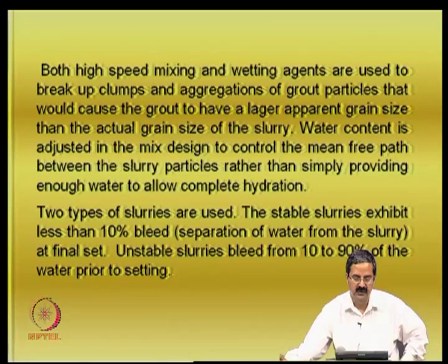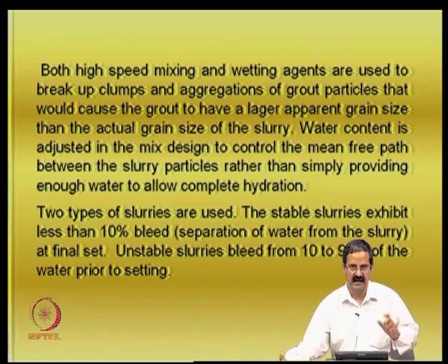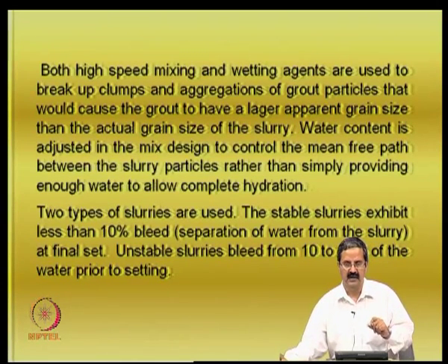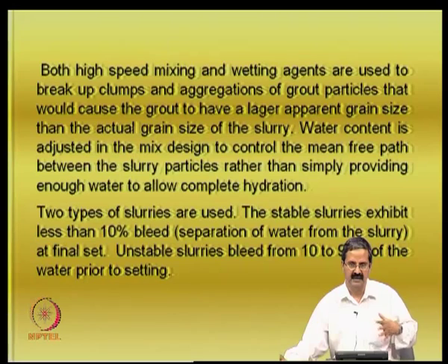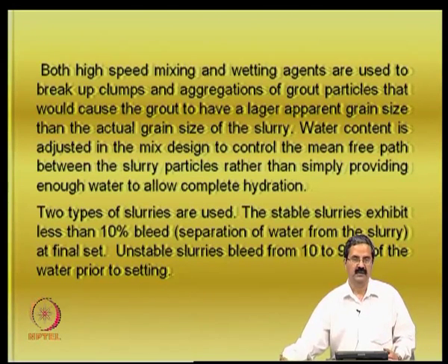In the case of cement mortars, the water cement ratio is somewhat critical, and we have a lower ratio. But here the objective is to have a lot of water available so that the mean free path is somewhat higher, there is water movement everywhere, and there is flowability also, compared to what you see in other cases.